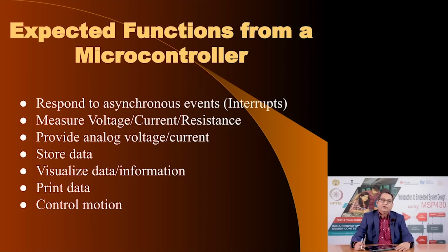One, it could have a device such as an ADC for reading analog voltage, it can have a device called a DAC, a digital to analog converter. In many cases, a lot of cases, a microcontroller does not have an explicit digital to analog converter. But there are other methods of converting digital voltages or digital numbers into analog voltages or currents and so on, using a method called pulse width modulation.